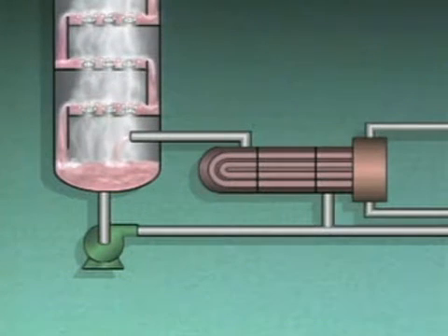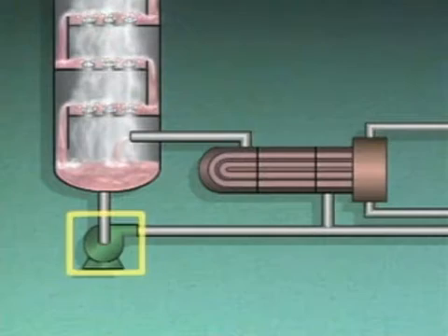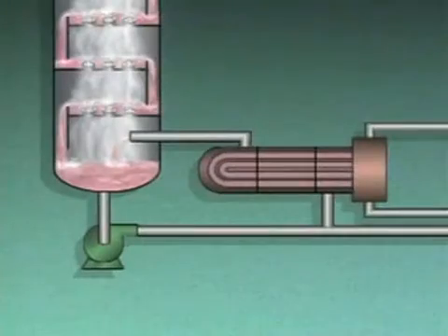of circulating mixture. So there has to be a sufficient level of mixture in the column, and the reboiler circulating pump must be running. In this system, circulating the mixture prevents it from overheating once steam is supplied to the reboiler. If some mixtures overheat, they can bake onto the reboiler tubes, fouling the tubes and restricting the heat transfer from the steam to the mixture.